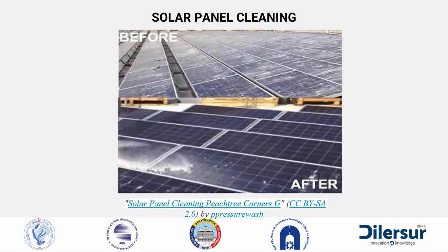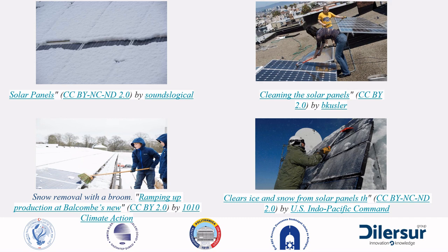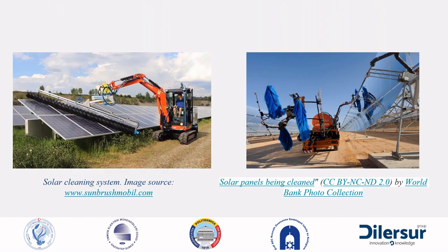Depending on the size, installation height, available utilities and equipment, etc., the cleaning of solar panels can be done using pressured water, soap, and various tools or special machines. Recommendations regarding solar panel cleaning. Abrasive sponge or soap should never be used for solar panel cleaning, to avoid scratching the glass. The best way to clean solar panels is by using soft materials and biodegradable soap.